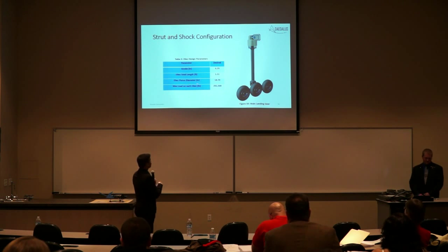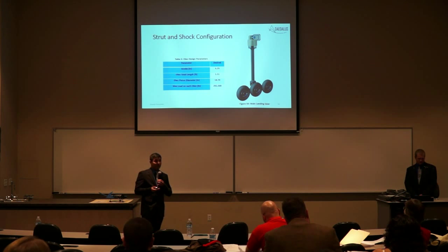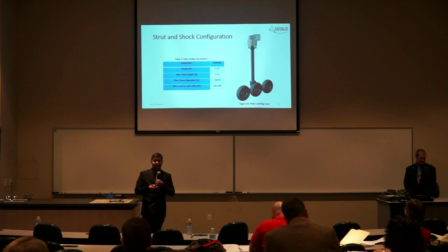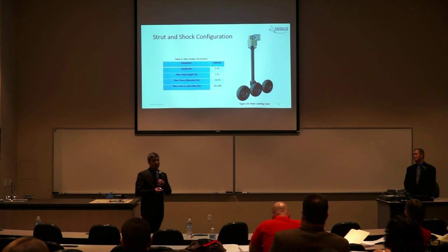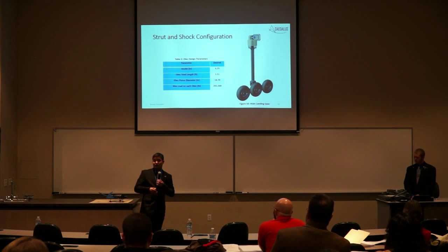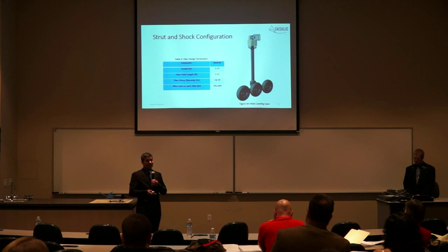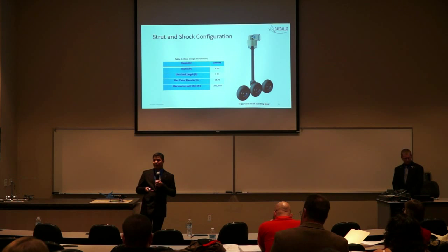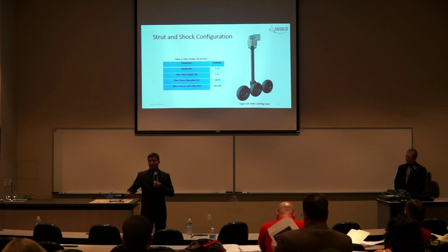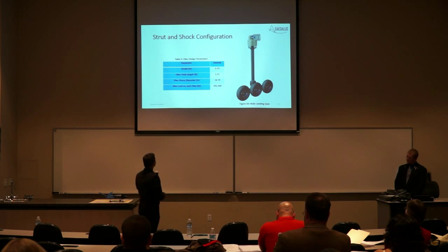As well, we followed Daniel Raymer's book and went on to oleo shock absorber sizing. The minimum required stroke is 6.29 inches and an aluminum piston diameter of 18.7. This will be further developed in detail design, probably by choosing one from a catalog. As this aircraft is trying to keep the cost as low as possible, we want to choose parts that are off the shelf from the manufacturer.